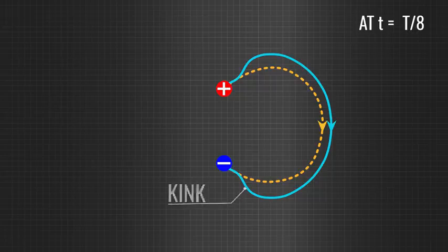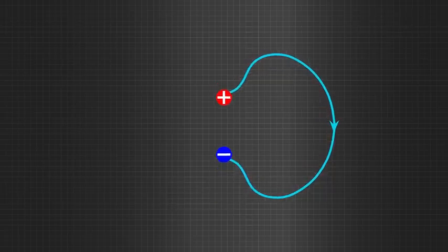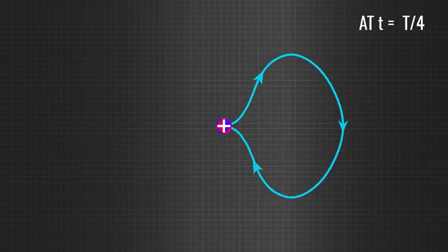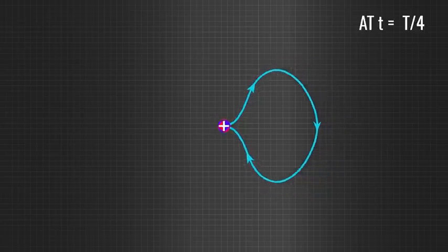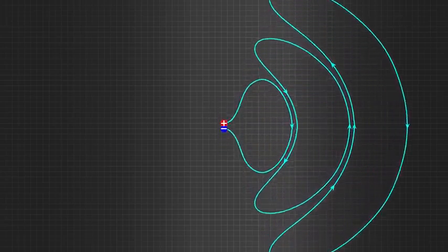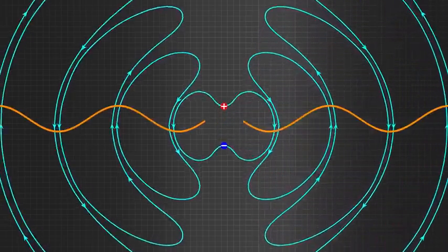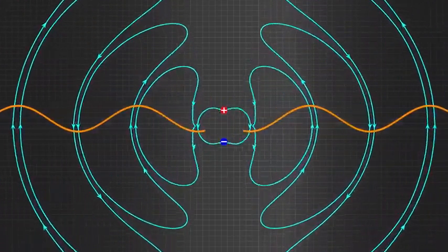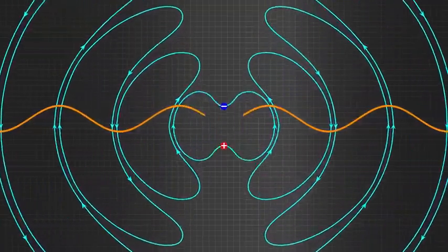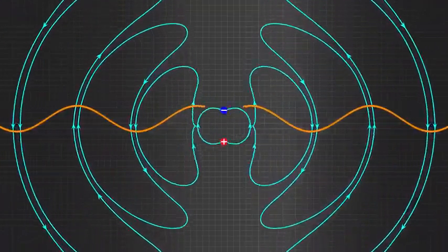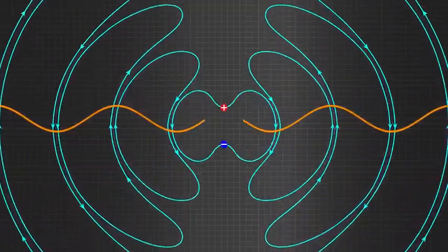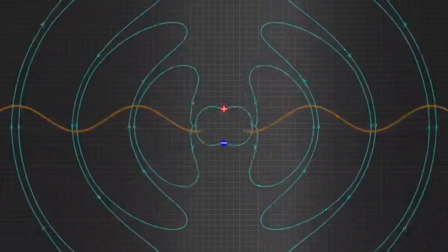This deformation is continuous since there is continuous acceleration in the charge. When 2 charges meet at the central point, the deformed line also meets there. After that, it detaches and radiates. This radiation travels at the speed of light. If you plot an electric field intensity variation with respect to length, you can see that the radiation we have produced is perfectly sinusoidal in nature. Please note that this varying electric field will automatically generate a varying magnetic field perpendicular to it.